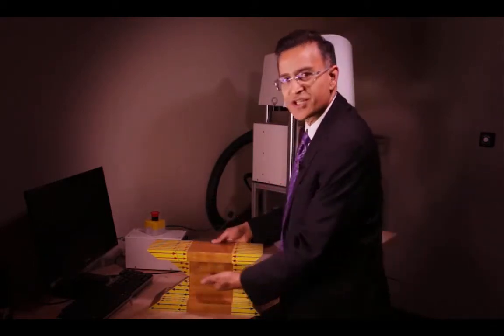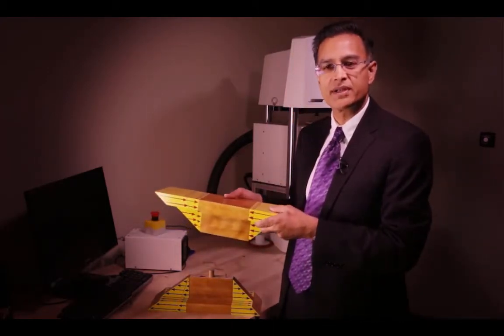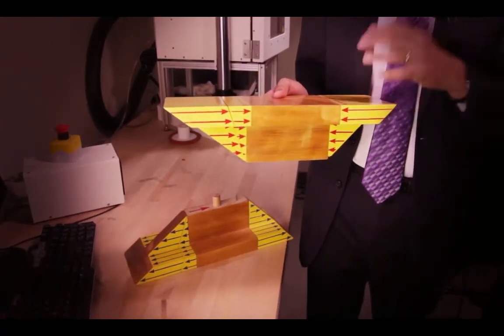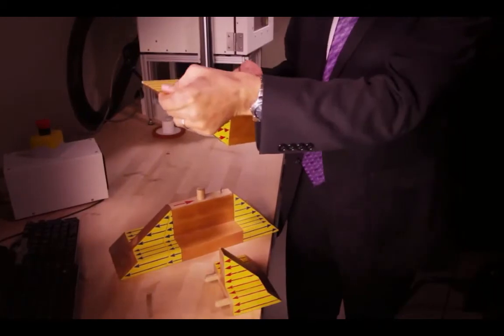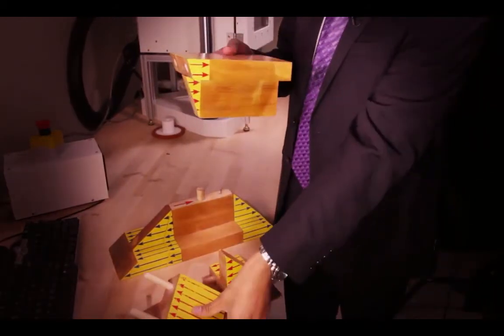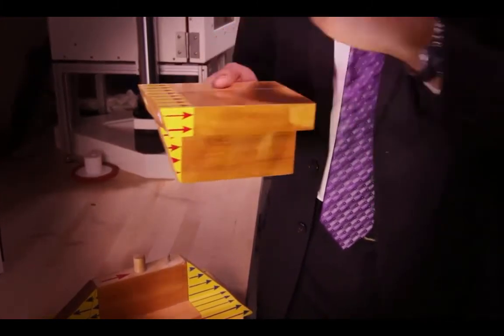And so to get to the shears, what I'm going to do is make a horizontal section cut in my differential element. So if I do that, I have stresses on both sides for my moments, and those stresses are different from each other. So let me go ahead and subtract off the same amount of moment and the resultant stress from both sides. So if I go ahead and do that on my beam, you'll see I have some stress that's due to the differential moment from one cross section to the other.